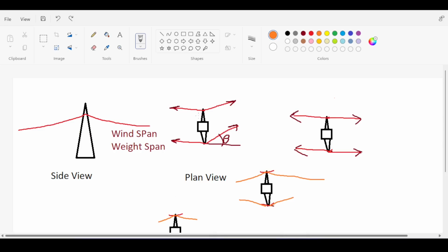The first load that you would think about is the own weight, meaning that a tower has an own weight, and this is something from structures, like the forces on the tower itself, that any engineer can calculate. You have the own weight of the tower, you have the wind load applied on the tower, and you have all kinds of other loads that a structural engineer can easily calculate and use. So in this video and even in the modeling video, I will be ignoring the wind loads applied on the tower, but I will keep reminding you that I'm ignoring this because I want you to try to calculate and apply it on the different elements.